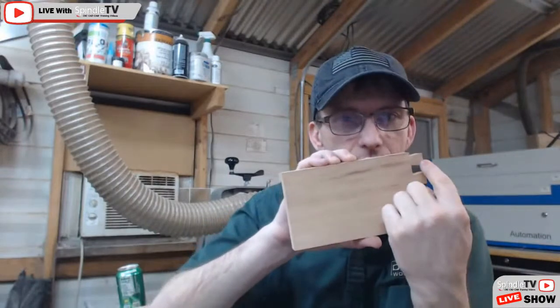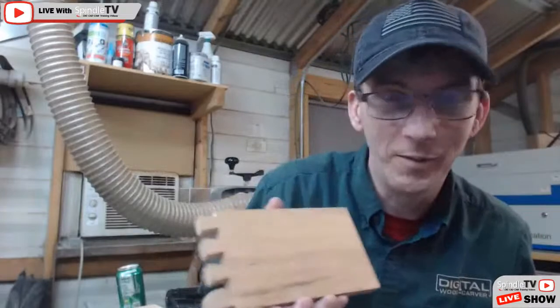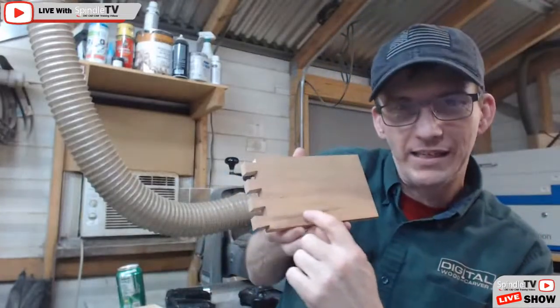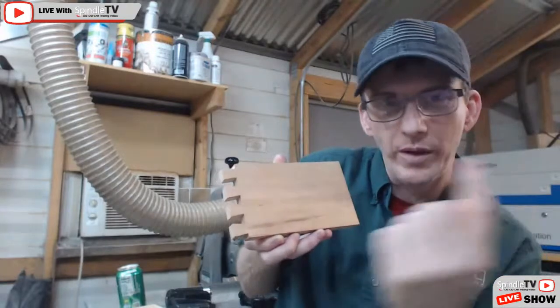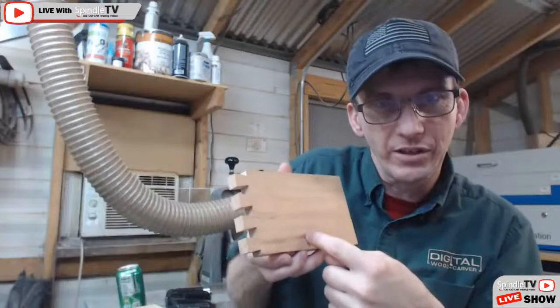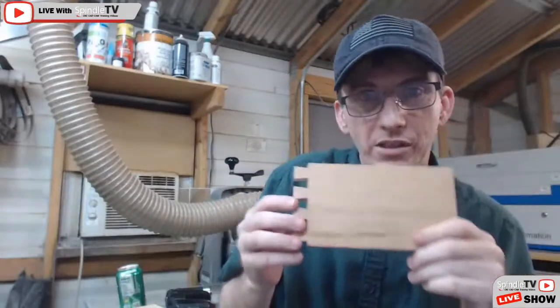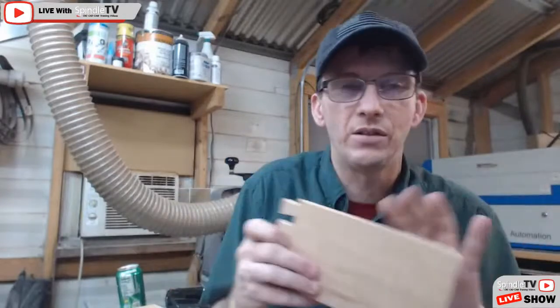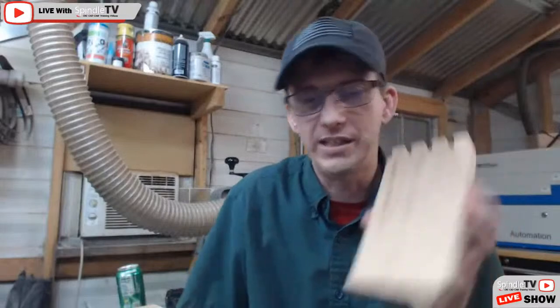There's going to be, right along the bottom on the inside, a 3/16 inch groove all the way around for the bottom of the box. And then there's also going to be a 3/16 inch groove for the dividers to go into. So these parts are not finished yet. Once they get the dovetails on them, they still have to go on the table and get their finishing cuts and everything.